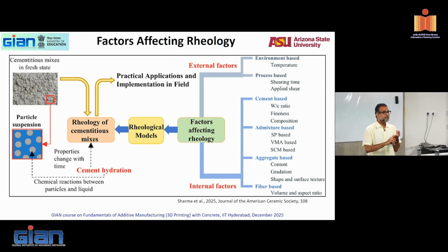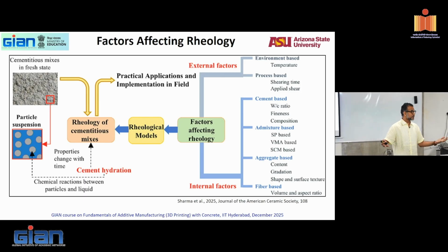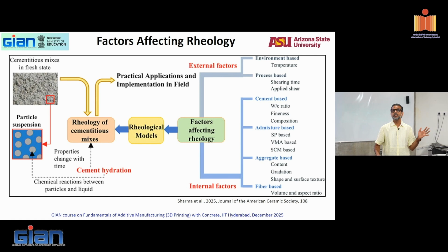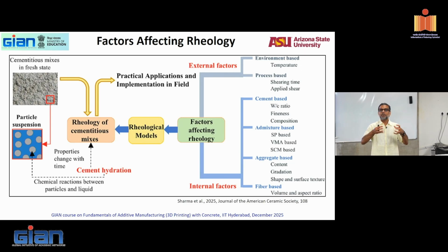Shape of particles is very important. Size of particles is very important. And particle sizes, you know that, right? Whether it's aggregate or cement, or cementitious materials, you have a range of particle sizes. Rheology is a big function of the particle sizes and particle shape, or generally particle characteristics. Particle characteristics affect how particles pack in a given volume, right? Spherical particles pack very differently to angular particles.